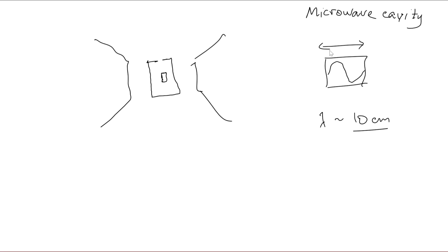So it would be resonant, which means you'll have oscillating electric and magnetic fields. And you can choose the geometry so that the field of interest, actually we are interested in the magnetic field, would oscillate in the right direction. So we make a cavity, and this is the big H. We will make a cavity in which the small h will oscillate up and down at this particular point. Now, why do we choose a cavity? A cavity basically allows us to get standing waves, and standing waves give well controllable amplitude.